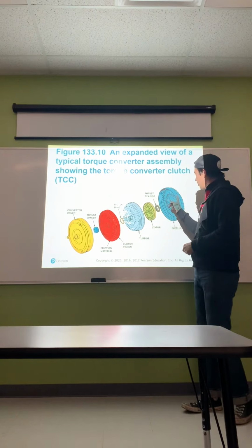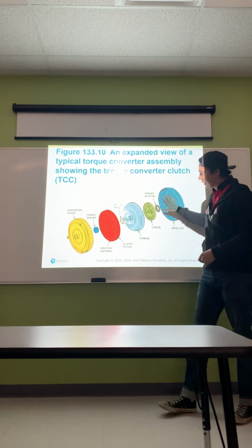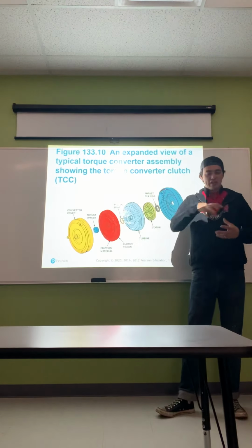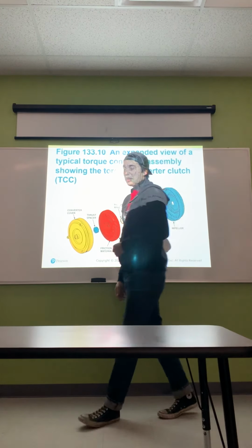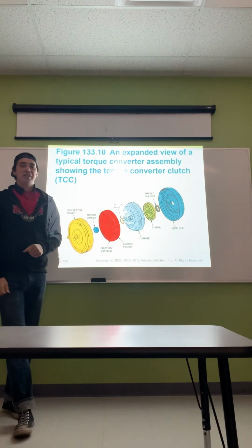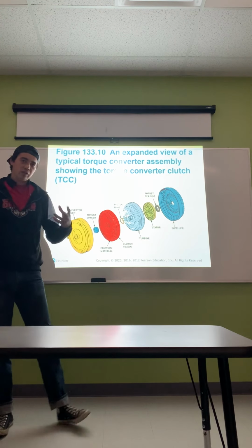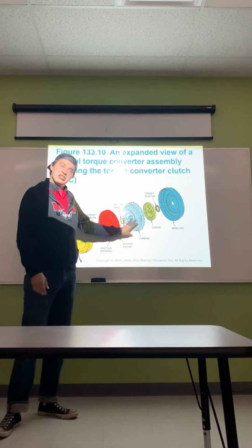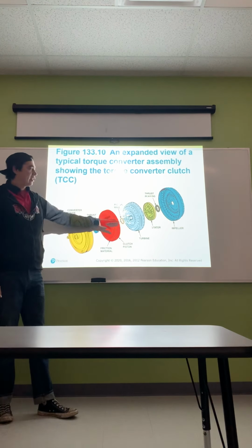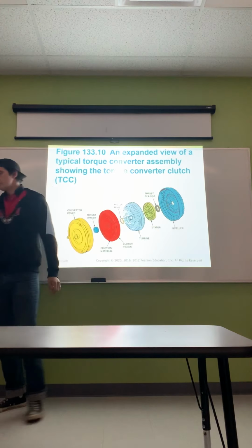So if you ever have a free torque converter and you want to see what's inside, you're not going to use it for anything, you're going to have to cut the welds off the impeller and the converter cover. But you can cut them open and pull it apart and see all the parts inside. I'm thinking about doing that with one of our torque converters here, just so I can show you guys. I'll do a little extra lecture on the breakdown of each part. But like I said, unless you're rebuilding torque converters, you're really never going to see these parts separate.